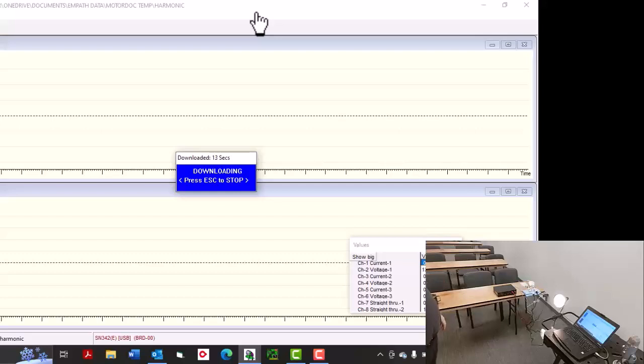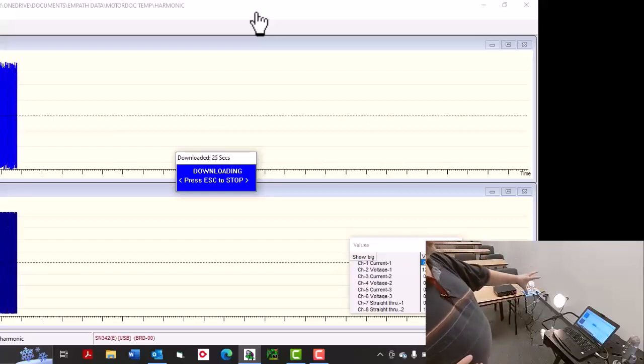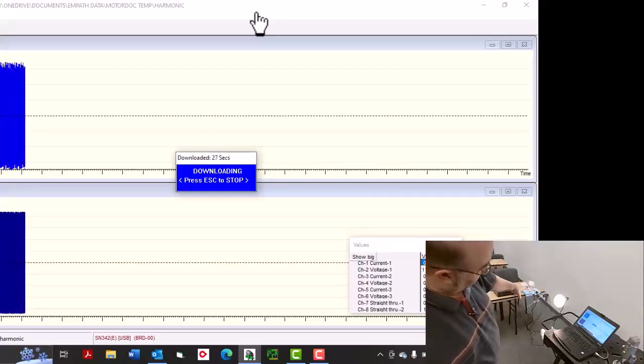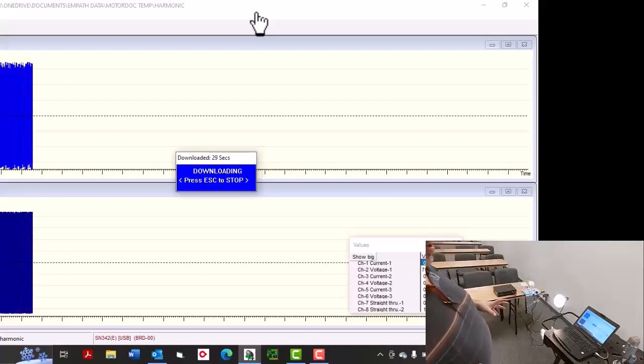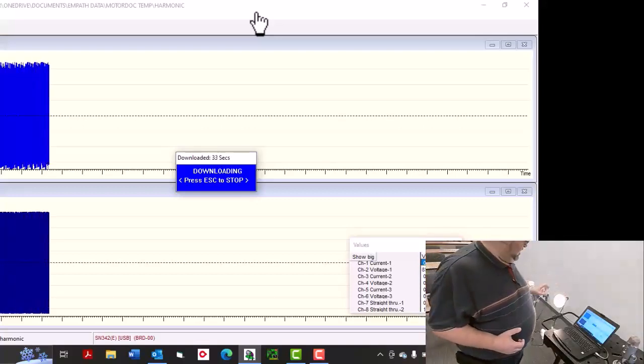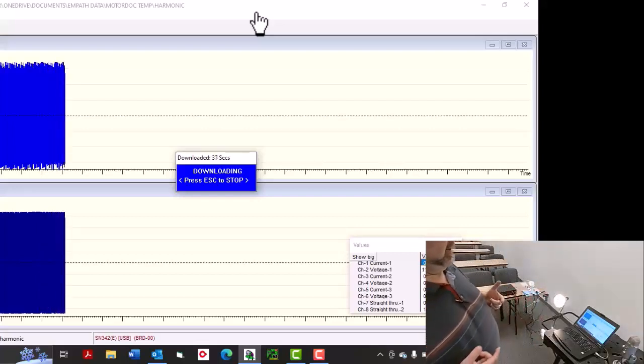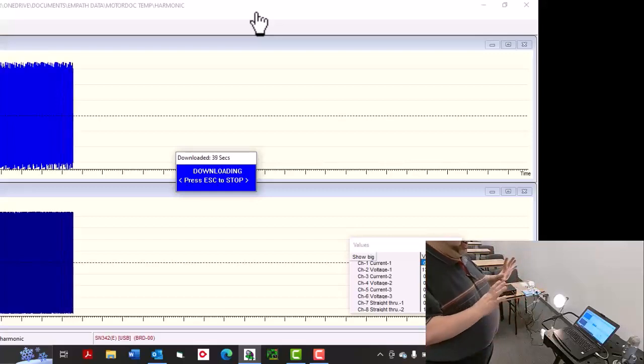Again, it'll take just a minute. And then, as I said, I'm going to go to the 10 time, so it'll be the equivalent of having 10 of each bulb on the system. So the voltage doesn't change, but the load would. So I'm going to simulate by using the second point on that, which is 10 times the current. So we look and see if I had 10 bulbs here and 10 bulbs there, and we're going to run the same thing over again.